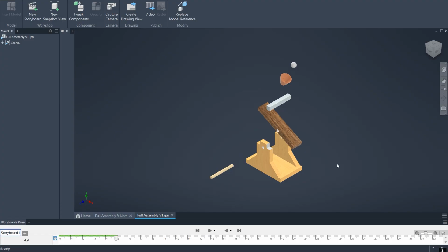So just to name the main components of the catapult, we have the cup, the stopper bar, the board, the base, and we have the rod. So the cup is there to be attached to the board so it can hold the projectile. The stopper bar stops the board from moving. So when it has that sudden momentum stop, the projectile will be shot over. Then we have the base, which holds everything together, and the rod is where the board can pivot and actually move and launch the projectile.